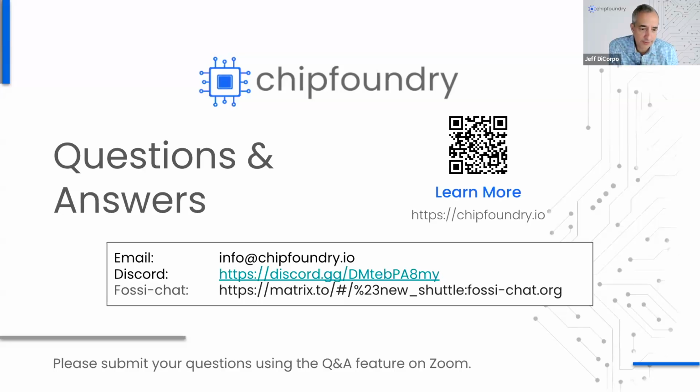You should also note that there is timing, obviously, as part of the PNR flow when you harden and run OpenLane, and there's more detail that you can provide around evaluating and reviewing those timing reports. In addition to that, there's static timing analysis that can be performed on a full chip level with Caravel integrated, and that's what Marwan was just referring to.